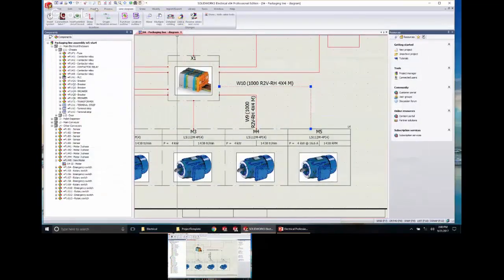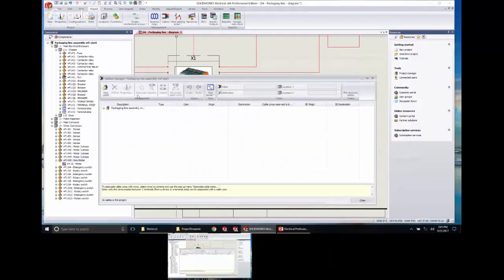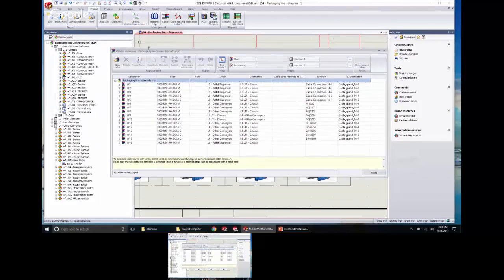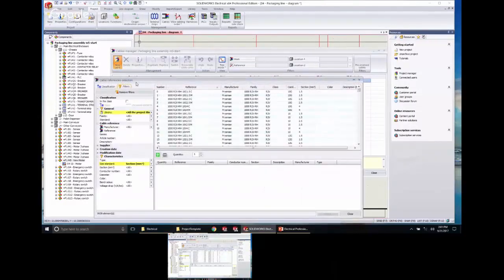Close that. So if you go to your project tab and go to cables, so project cables, this is where you would create those cables. Here you either create new cables or select manufacturing ones you already have. Notice you can only select new cable. Right. So a cable is always going to be defined by a manufacturing part. But when I select new cable, I'm saying I'm going to have a W23 cable or whatever, and it's going to use this manufacturing part. That makes sense? Okay, great.